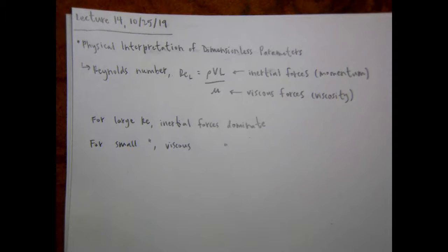We talked about how the Reynolds number of a flow influences its transition to turbulence, whether it transitions, and if so, where that transition occurs. There can be some flow disturbances, and if the Reynolds number is really low, the viscous forces tend to attenuate those and prevent or delay a transition to turbulence. If you have a high Reynolds number, the inertial forces and the higher momentum of the flow exaggerate those disturbances and cause a transition to turbulence to occur more quickly or with a higher likelihood.